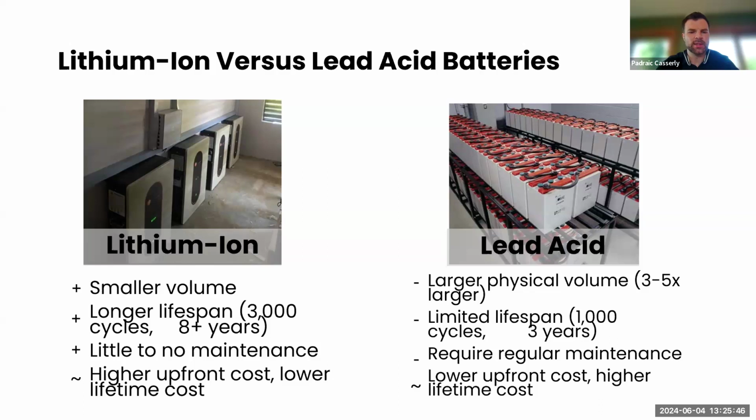Lithium-ion batteries can last 10 years or longer and require little to no maintenance. One drawback is that there's a higher upfront cost, but over the lifetime of the battery, it can actually be at the same cost as a lead-acid solution. So lead-acid batteries are larger in physical volume. They may last only 3 years, which means that they need to be replaced frequently and they require regular maintenance.